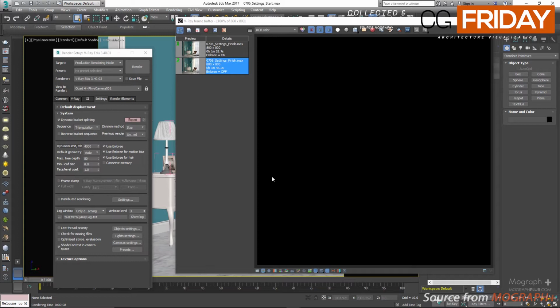First of all, what is V-Ray's binary space partitioning tree, or BSP tree? One of the basic operations that V-Ray must perform is ray casting, determining if a given ray intersects any geometry in the scene, and if so, identifying that geometry. We talked about raycasting in our previous sections. Now, the simplest way to implement this would be to test the ray against every single render primitive in the scene, or triangle. Obviously, in scenes with thousands or millions of triangles, this is going to be very slow.